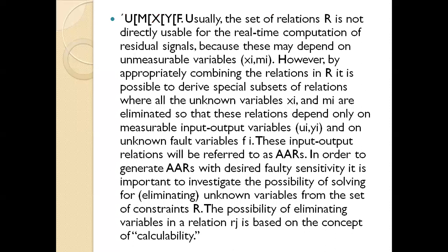Usually, the relation set R is not directly usable for real-time computation of residual signals because it may depend on unmeasurable variables. However, by appropriately combining the relations in R, it is possible to derive special subsets of relations where all unknown variables X and M are eliminated, so that these relations depend only on measurable input-output variables, U and Y. This input-output relationship will be referred to as an ARR.